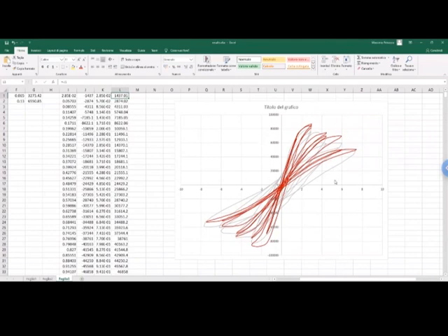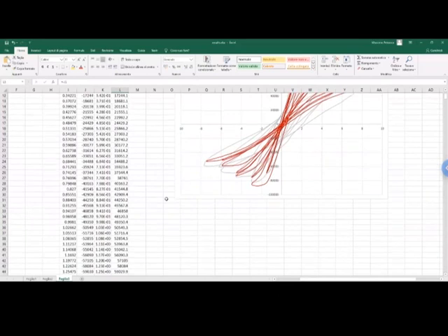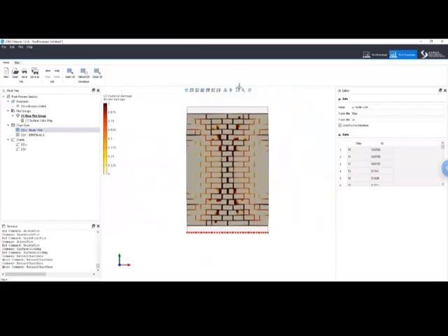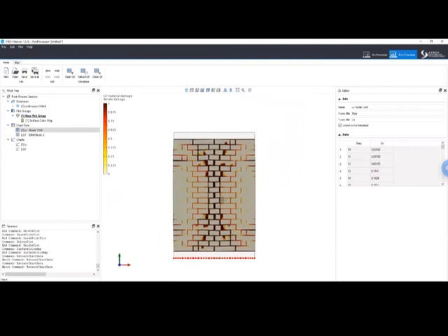So this is the output that we obtain, which is quite good with the experimental results. We just need to put probably some more plasticity, but in this case I just used those values, which is fine. You can try to play with the plasticity values to check if you can get better results here. So this is our example. You can see that it's extremely easy to do this kind of modeling. Probably the most difficult part was the CAD modeling of the microstructure.